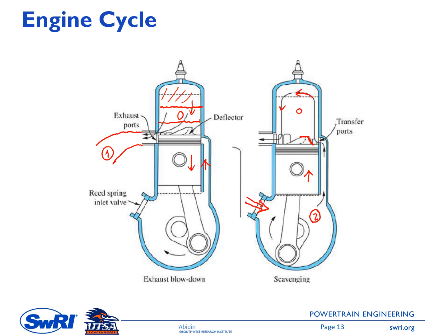Because the crankcase volume increases due to the piston movement toward top center, the pressure inside the crankcase decreases, and at some point this intake manifold pressure, let me put number 3, so this P3 will be higher than P2, and then there will be a flow of the fresh mixture going into the crankcase.